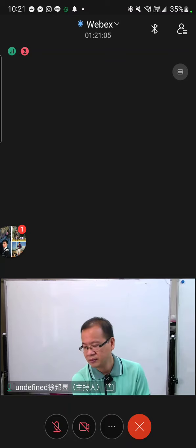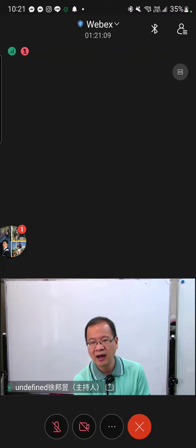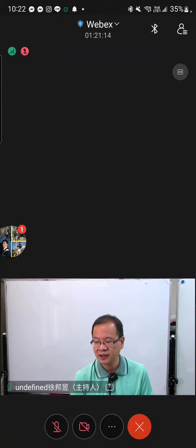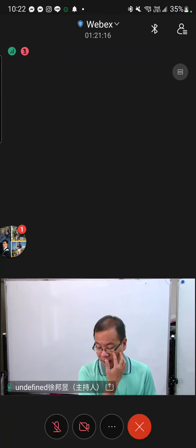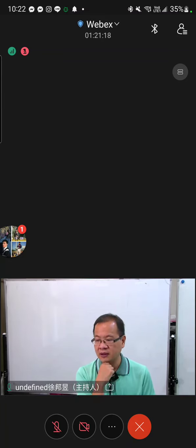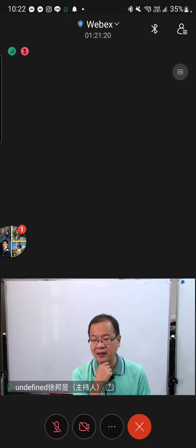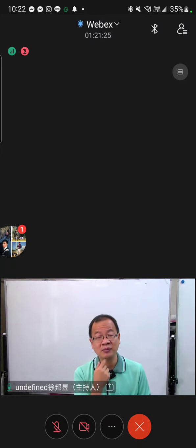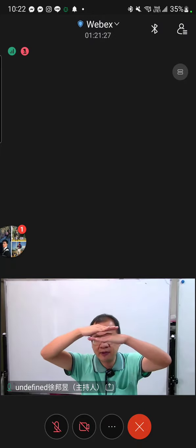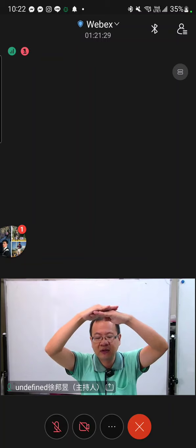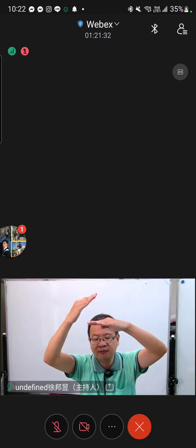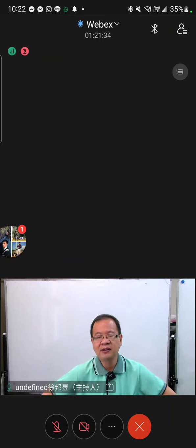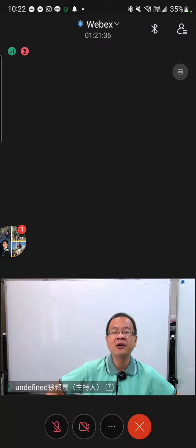So, purple: people found the failed circuits look purple on the soldering area. So they found that the different alloys are driven by kinetics. When you have this kind of interface appear at different atomic ratios, then you have trouble, because their mechanical properties are different on the interfaces. So it just pops up. They can no longer bond well because the mechanical properties are very different.